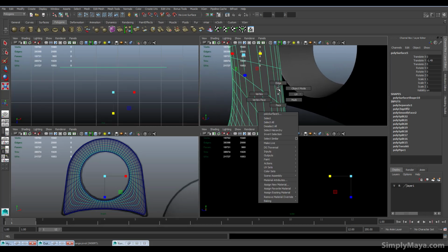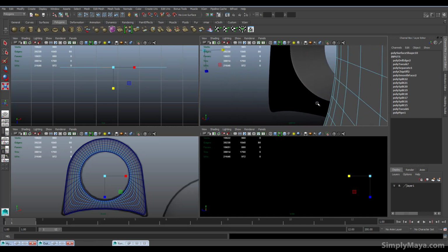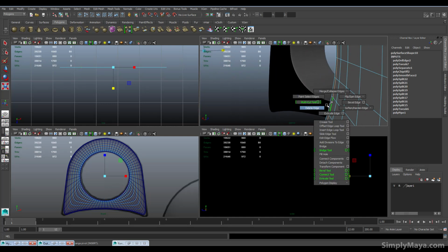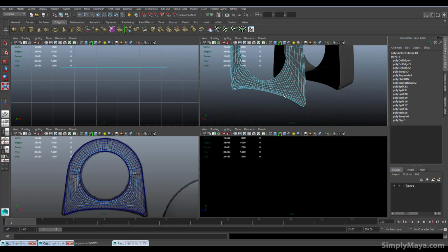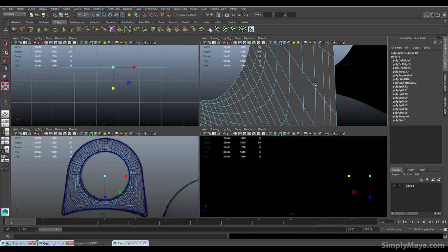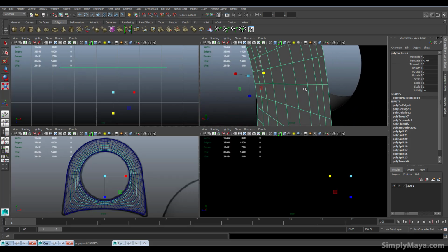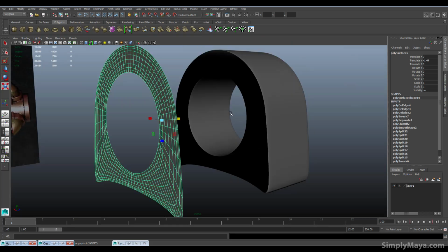Let's see if we could get rid of any of these edge loops before we come in and convert this thing out. So that one can go, I don't need too many in here. This one, also this one probably, and I can probably take out a few more if I wanted to lower the poly count on this, but retopology is really a subject for another day.